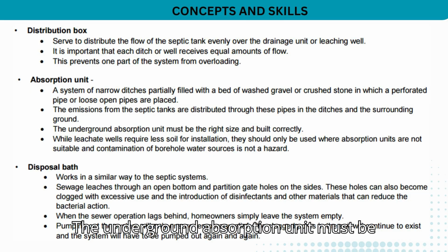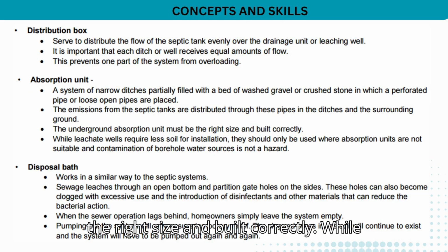The underground absorption unit must be the right size and built correctly. While leachate wells require less soil for installation, they should only be used where absorption units are not suitable and contamination of borehole water sources is not a hazard.